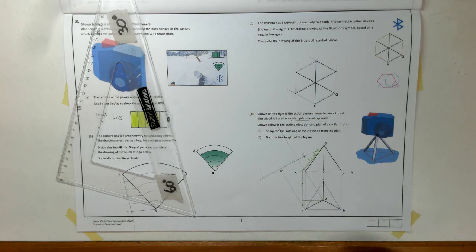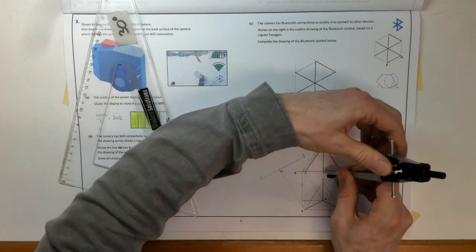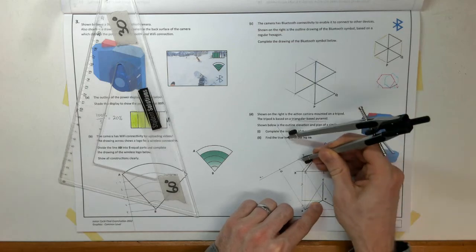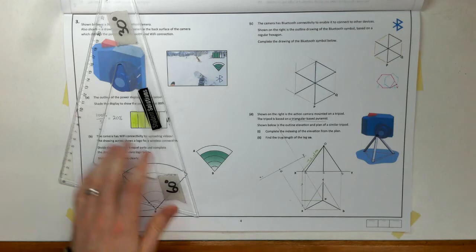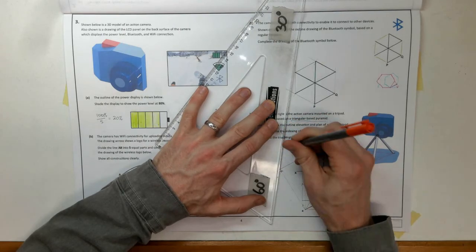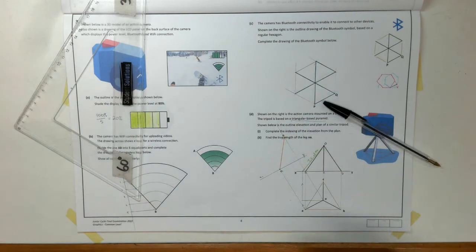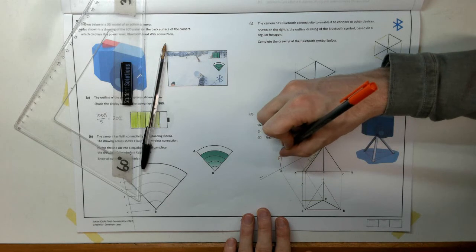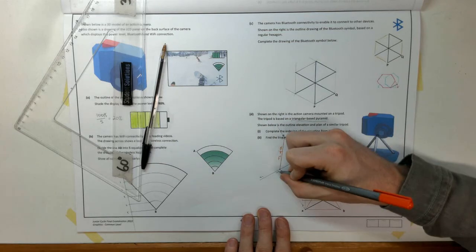Right? My point O then has a height of that, and I'm going to follow it down to O up here. It's going over my drawing a little bit, but there we have O, and I'll just use a different colour to highlight this, but it's the same measurements. There's O to A. I'll label O there. So this is also true length of OA. Projecting out there, and that's at 90 degrees.